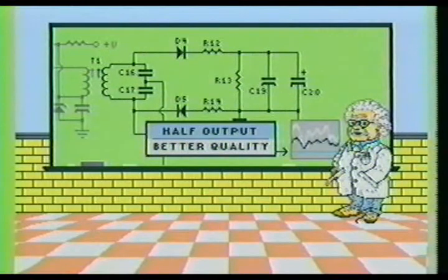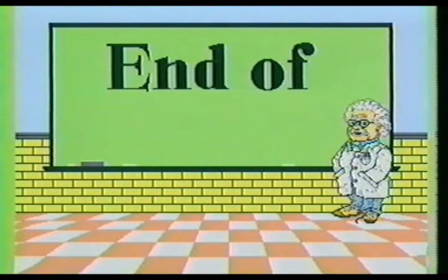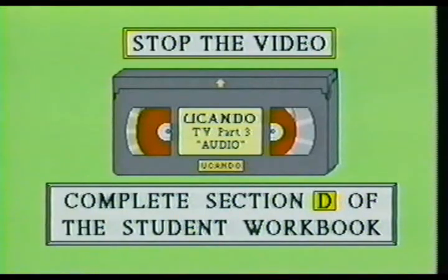The normal audio output level of a ratio detector is half the level expected with other FM detector circuits. This is because the ratio detector only rectifies or uses half of the incoming RF signal. This concludes review number 4. Now stop the video and complete section D in your student workbook.